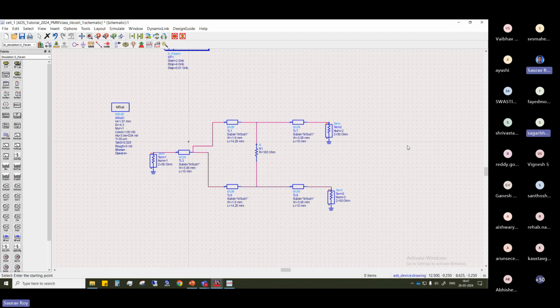No, no, that is not the way a microstrip line will work. A microstrip line directly says it should have a ground at the bottom. You must have a substrate ground for the substrate. The microstrip line should be connected to the ground layer. The microstrip line definition, if you remember your studies, is defined only as that: it must have a ground at the bottom, and at the top layer we have a patch.